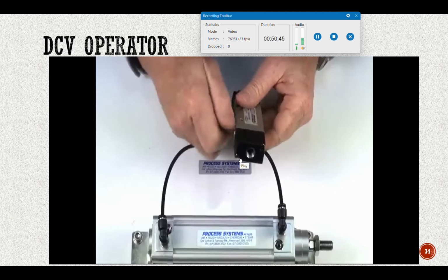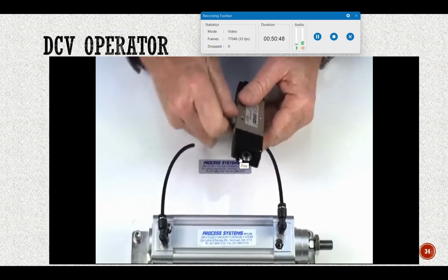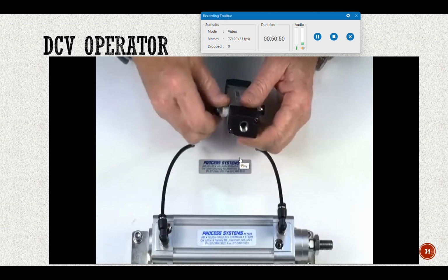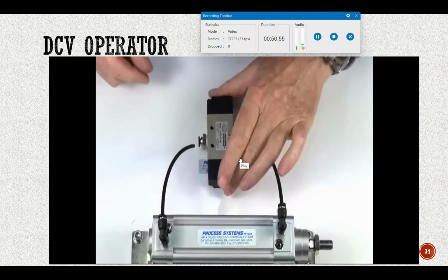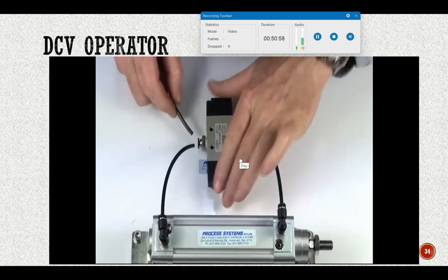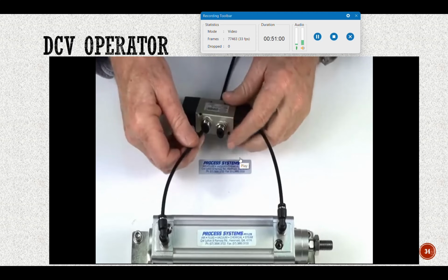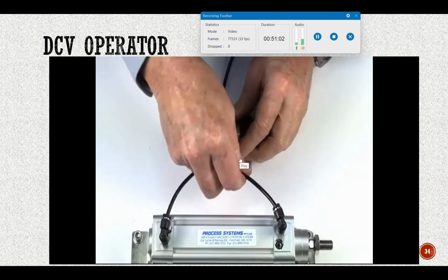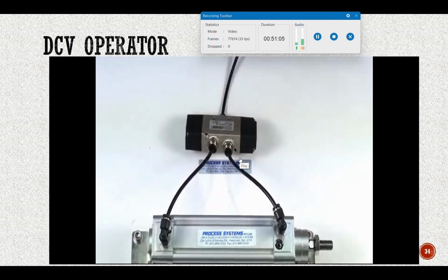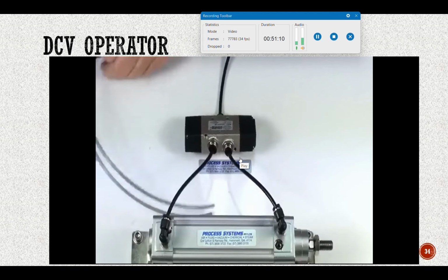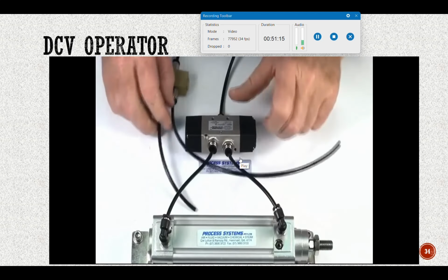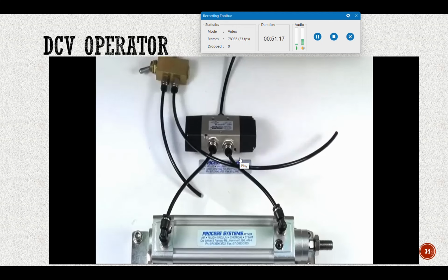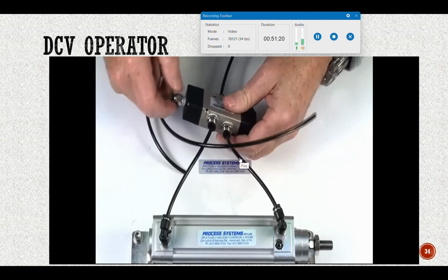Put a supply into the inlet port. To do this, we'll put an air supply in the inlet port of this valve and connect it onto this double acting actuator. And we'll use a 5/2 pilot valve, one of our mini 1/8 M5 valves. Supply in there, and we'll have to put 2 fittings into either end of this unit.